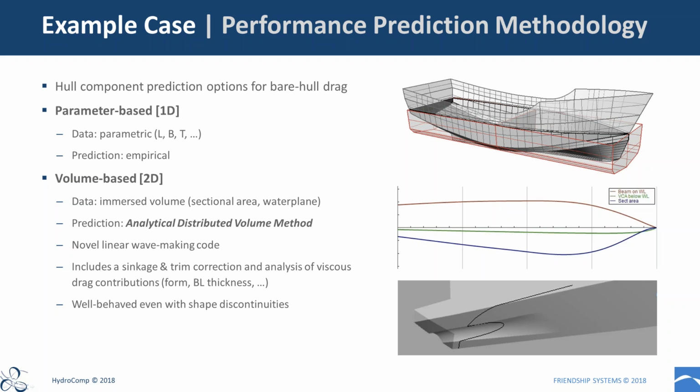By looking only at sectional area, waterplane distribution, and the vertical immersion of the sectional areas, we eliminate those problems. And so this method is extremely well behaved and provides no disruption in an optimizing session where you're going to be looking at many, many different variants.